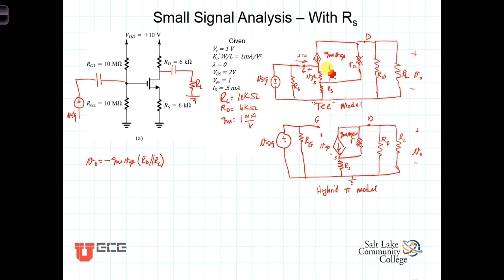Now in this model, where we have both the transconductance resistance 1 over G sub M and R sub S, and by ignoring R0, those two resistances are in series with each other. VGS is the voltage across this resistor, and VGS is in fact a subdivided portion of the voltage here at the gate. Now in this situation where we haven't modeled a source resistance, the voltage at the gate is just V sig. We'll do it in two steps, but first of all, let's just write VGS equal to V sub G, the voltage at the gate, let's make that a lowercase v, lowercase g, times the voltage dividing ratio 1 over G sub M divided by 1 over G sub M plus R sub S.